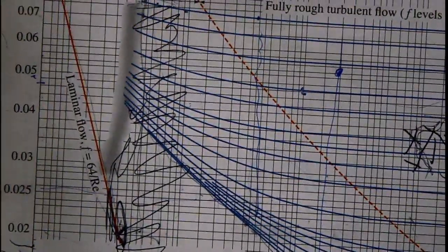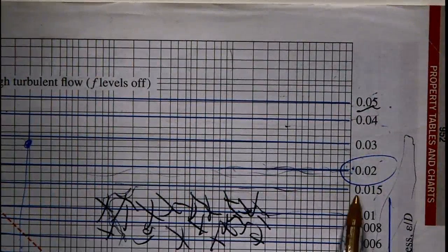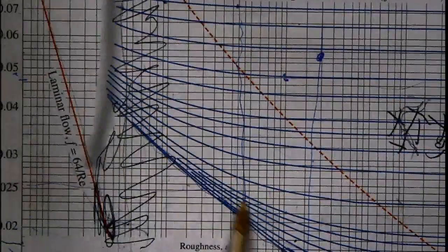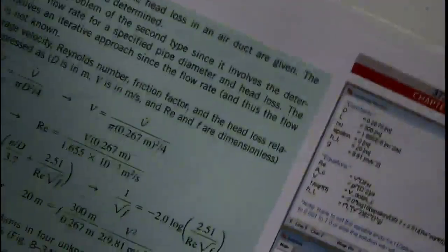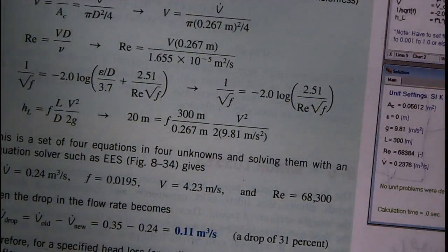So, see, again, the Moody diagram is so powerful in the fact that you'll know if you're in the transition regime, whether you'll know if you're in the fully roughened regime, whether you're in a regime where Reynolds number is actually important. So, this is okay, right? Your book is okay, but hardly the end.